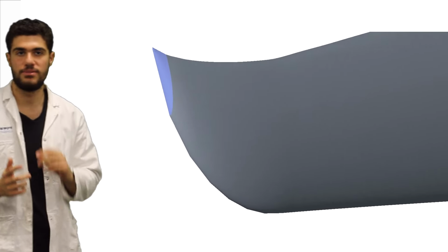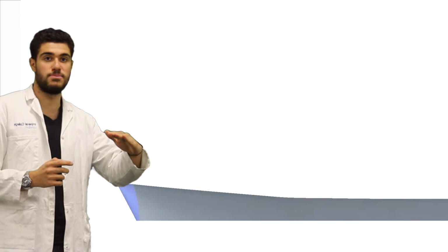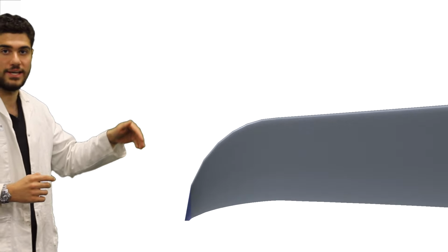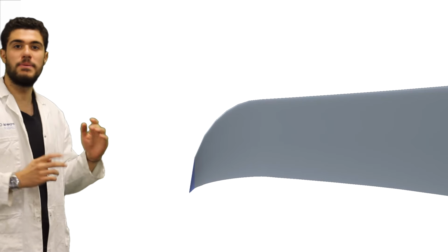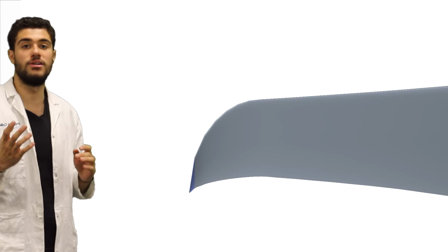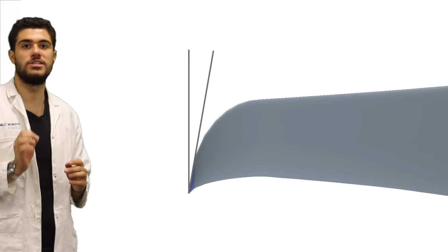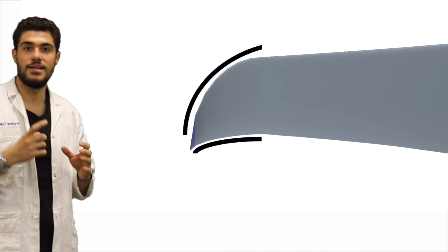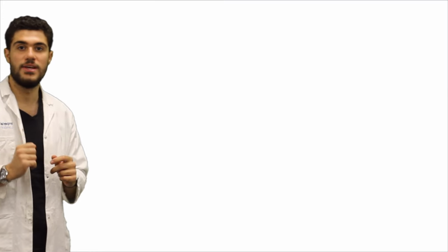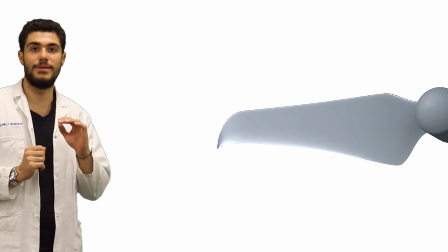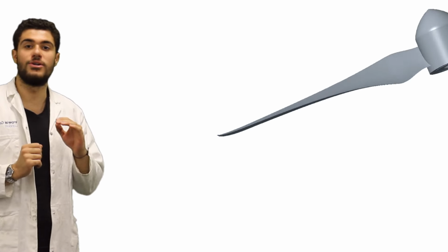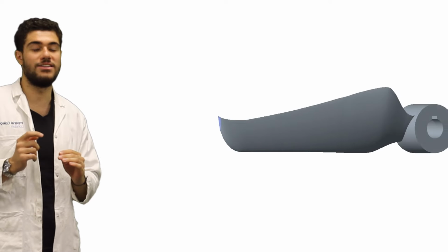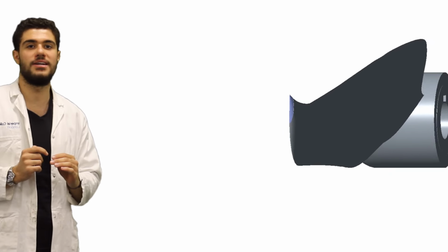For an effective Shark tip, the trailing edge needed to be as thin and as sharp as possible, whilst maintaining a rounded edge with a sharp corner. The sweep and rake angles were studied from the extent of material available, and a sweep angle of 15 degrees was chosen. This was then molded by two ellipses to provide us with the chord lengths and positions for the airfoil sections. A smooth finish is also required for maximum benefit, but it was also a challenge to input that in Creo Parametric and to manufacture, but worth the time dedicated to it as it should positively impact our power output.